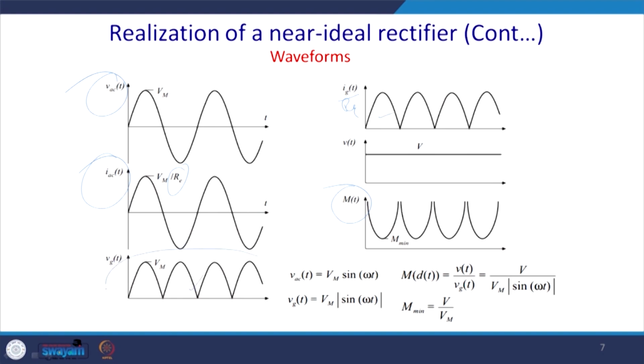This will automatically come, you do not have to do anything for the rectification, but the DC to DC converter will force this current to be like this, and ultimately the capacitor will ensure that your DC voltage after the isolated DC to DC converter is this, and for this reason your DC to DC converter will have this kind of modulation index.